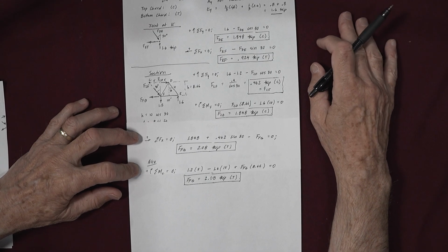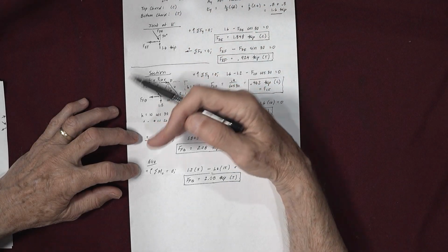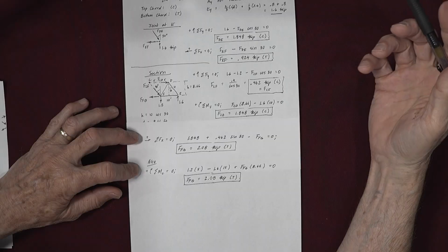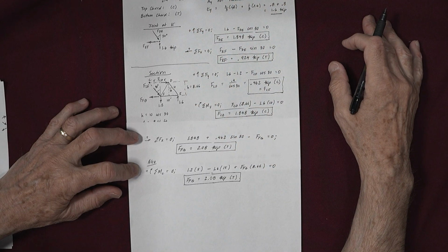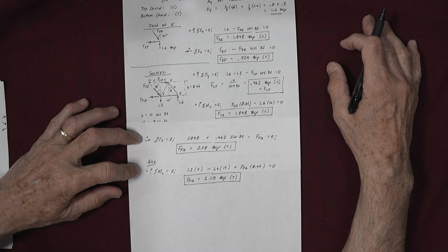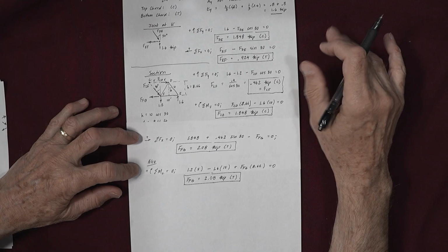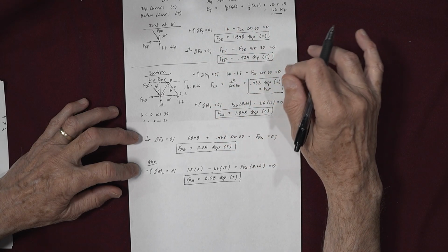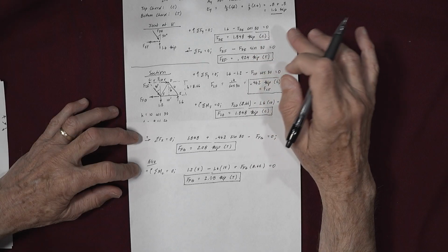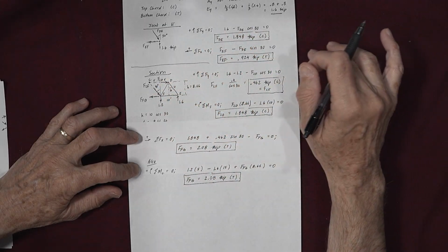So this is an easy truss. We've got the two parallel chords. We only have the one unknown with the y component in the vertical direction. There are no zero force members on this truss, so we don't need to worry about that. And we did a joint and a section, which is typical on an exam. They give you a truss, and to solve one or two answers involves a joint, and to solve for other things involves a section.